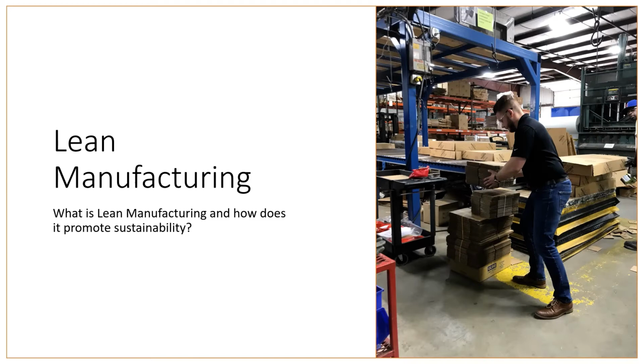Sure. Good question as well. The two pieces, as it relates to the transformative versus the casting type, is that when you're casting, as I described, it's a bit of a manual process. The major benefit to a casted part is that you can often create things that you would not normally be able to create, or that would be extremely challenging using forming or rolling methods. So casting allows you to create different things a little easier than traditional transformative methods. Now, casting can be more expensive, but if you're trying to achieve a certain shape and there's not another way to do it, that's your best option.